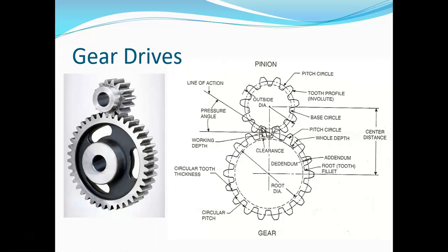And if that doesn't make sense, let's back up a little bit and go a little bit simpler. If you have a gear that has 25 teeth and you have another gear that has 25 teeth, meshed together, 25 divided into 25 is 1. It's a 1-to-1 ratio. One gear turns one full revolution, and the other gear turns one full revolution. So that's a 1-to-1 ratio.